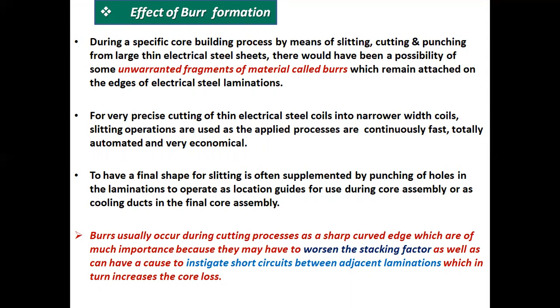Burrs usually occur during cutting processes as a sharp curved edge, which are of much importance because they may worsen the stacking factor as well as cause short circuits between adjacent laminations, which in turn increases the core loss.